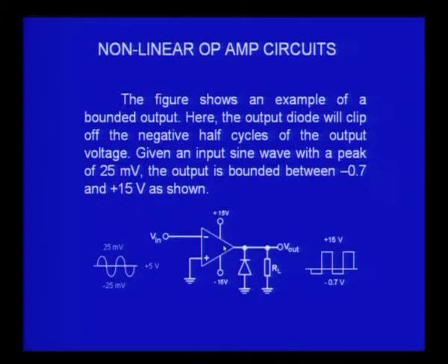If we measure, the input is a sine wave of about 25 millivolts peak amplitude, and that is enough for us, because we require only plus or minus 150 microvolts above 0, and one of the inputs is connected to 0. Therefore it is a 0 crossing detector now, and when the input goes beyond 150 microvolts or so, the output will become minus VCC.